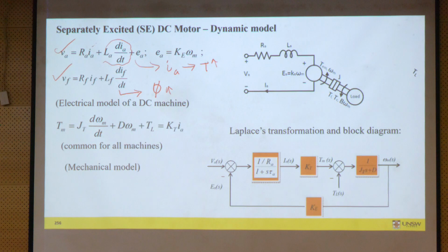On top of that, the current and voltage quantities are DC, right? That also makes control design easy. But if we want to analyze the transient response of a DC motor, we still have to consider this di/dt and dif/dt, and our torque equation also has a differential term, right? Acceleration, a time varying quantity, so it's also a differential equation.